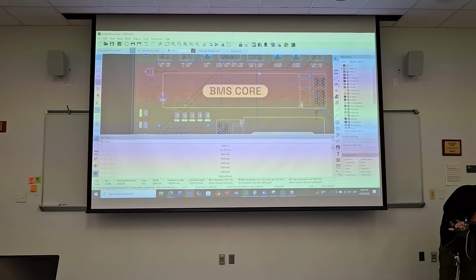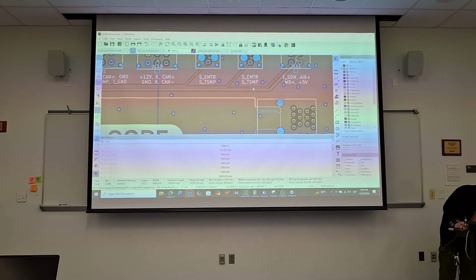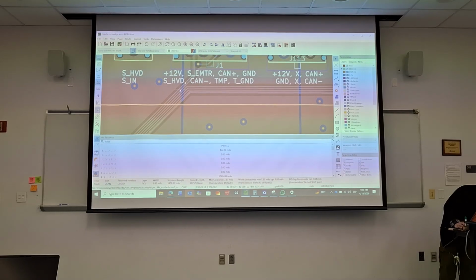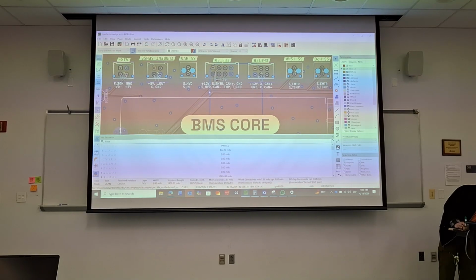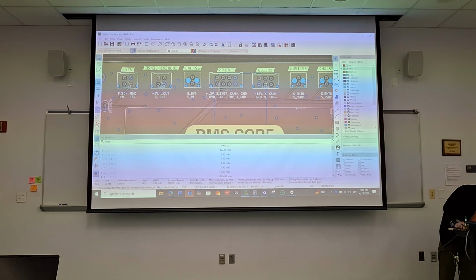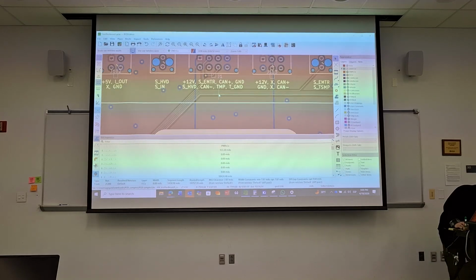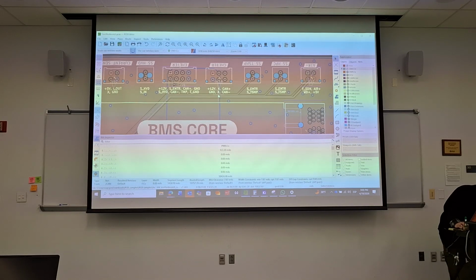So I see this right here, right? These sense lines that are crossing these split power planes, and those are causing huge loop inductances because they don't have a reference. Or if anything, here, they would have to go here, but what's hurting this is these are sense lines. They need a ground reference, but their current reference is power.